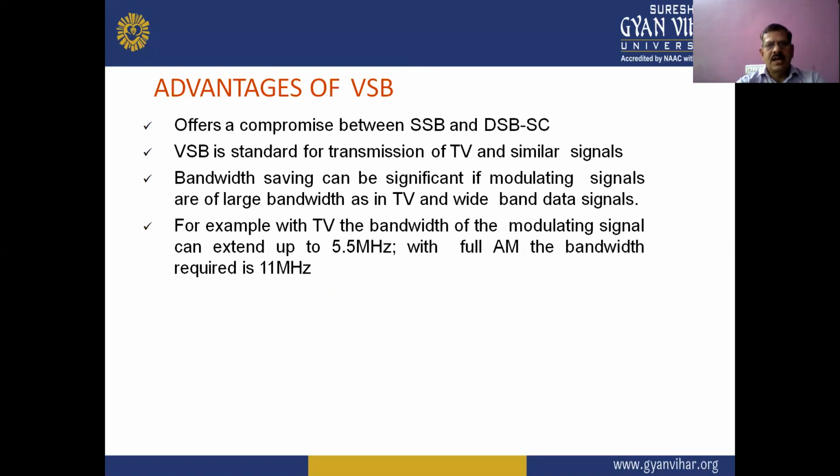And next, what are the advantages of VSB signals? So there are many advantages of VSB signals. First one is it offers a compromise between SSB and DSB-SC signals. VSB is the standard for transmission of TV and similar signals. The bandwidth saving can be significant if modulating signals are of large bandwidth as in TV and wideband data signals.